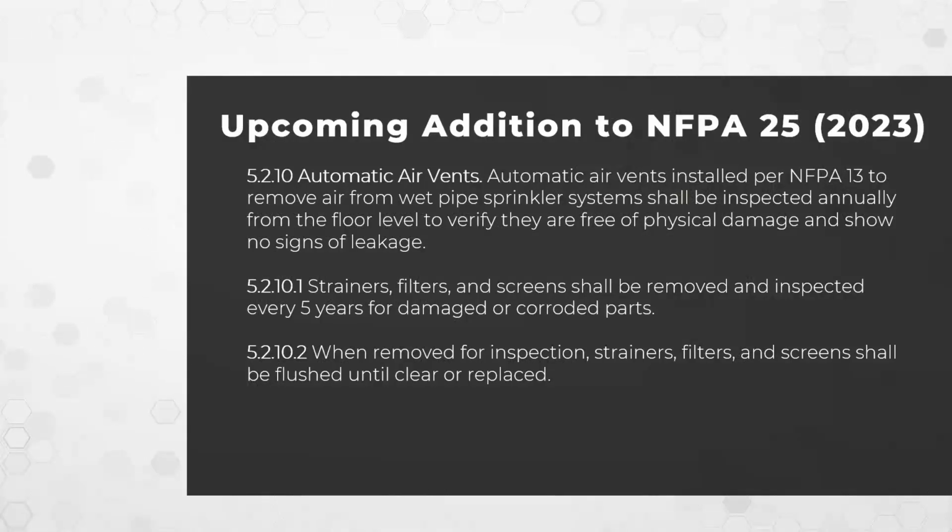One note of concern: in the upcoming NFPA 25, the building engineer and building contractor that put in these systems hand the building owner the NFPA 25 book when they commission the system, and the best practices for our industry are all detailed in there. NFPA 25 is the inspection, testing, and maintenance of fire sprinkler systems.